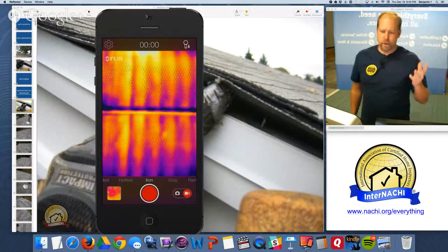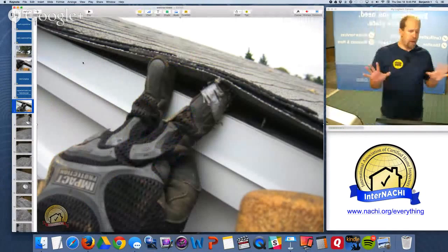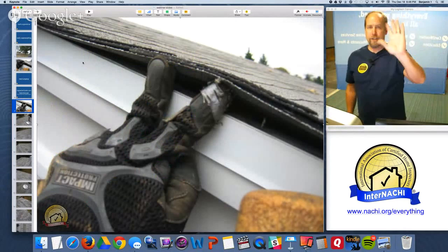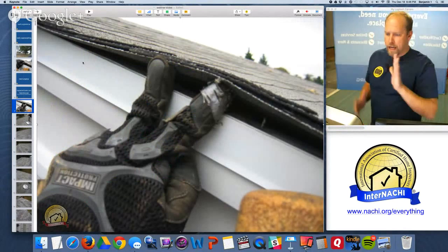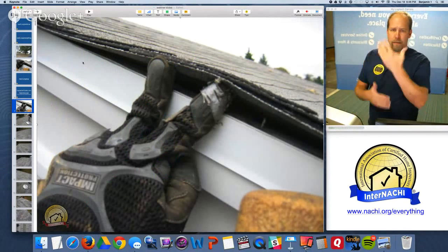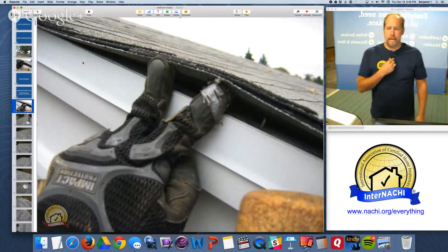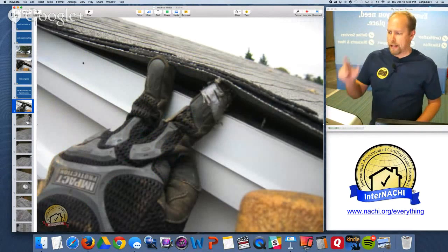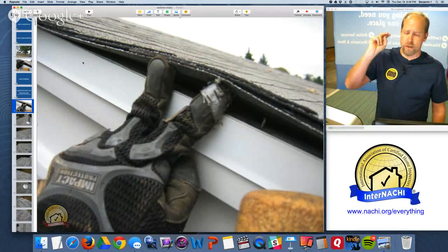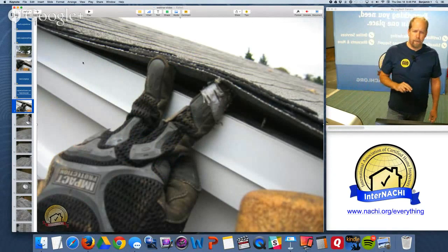But one of the best tools that you can carry is absolutely free. Every home inspector should carry one. Get your hand. This is one of the best tools you have. It's really sensitive. If you're looking for drafts or cool air, the back of your hand is really good. And I always put my hand in my inspections. Get my hand in there, and that's why I wanted to show you this picture. I'm identifying 2 layers of roofing shingles, asphalt roof covering materials, and I'm taking a picture of it too.